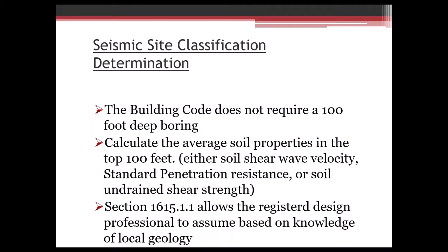So after we determine how many borings we're going to be doing, we then need to determine how deep we're going to drill. This is again going to be based on a lot of the conditions that we know, things that we know about the soils in an area, maybe the depth of bedrock that we anticipate. Maybe bedrock's not critical for that structure.